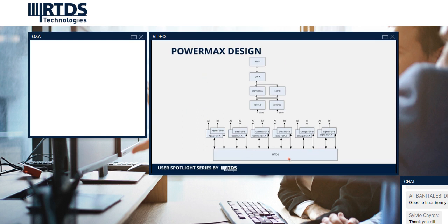What we do is we use RTDS to generate all field data, especially required for stability, for the load shedding system, for the generator control system, and then eventually even some amount of SCADA for the sake of populating the HMI. So we have what we call front-end processors. This is like how it is sometimes in the field, we set up so many FEPs spread over an area. They feed the primary source, and then there are centralized FEPs. And then that data is fed into load shedding processors and generator control systems.